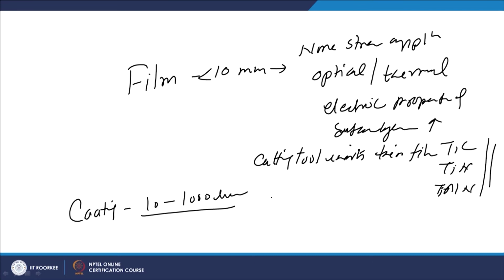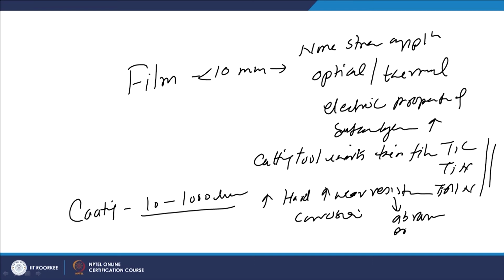They are used for increasing the surface layer hardness, increasing the wear resistance, increasing the corrosion resistance, or where a moderate level of stresses is acting. So, like increasing the wear resistance under abrasion, erosion, adhesion, etc. For those purposes, all these coatings are used.